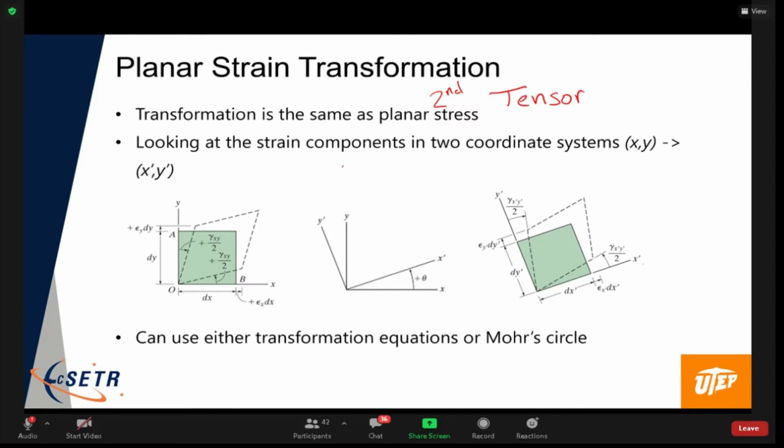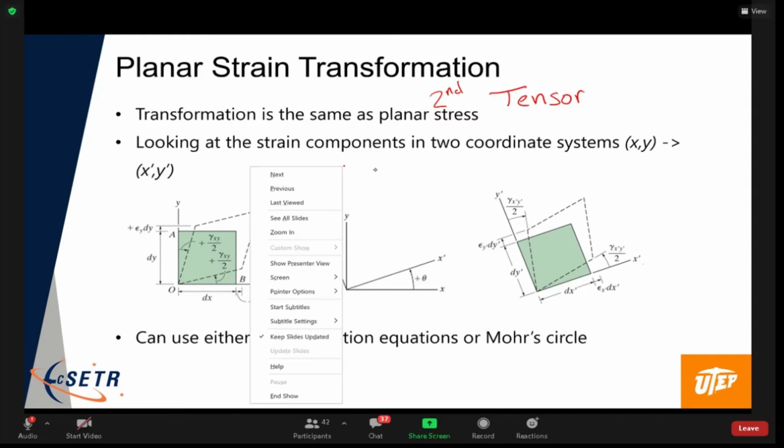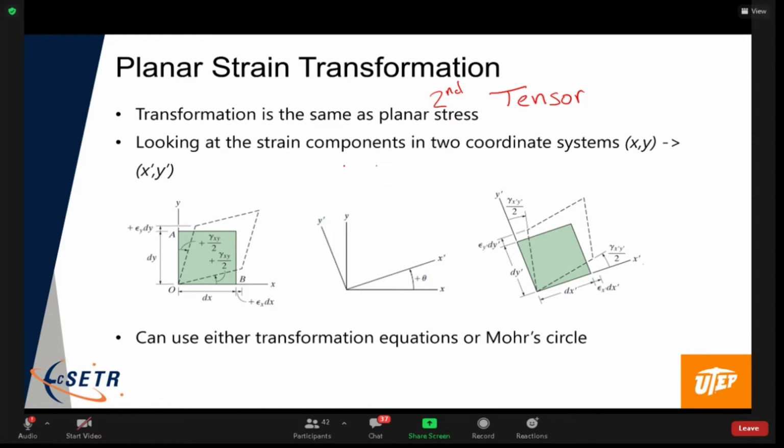So when we talk about, like, the shear stress tau xy, this is one direction and this is another direction. The x direction is the cutting face, and then the y is the component. For strain, it's the same deal. The 2 directions: one direction is in what direction are we looking at the change in stretch, and the second direction is which direction is it actually stretching in.